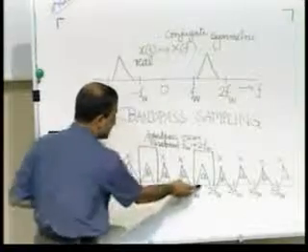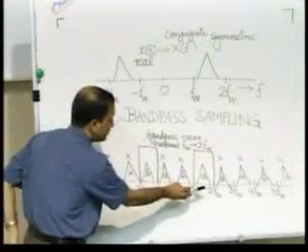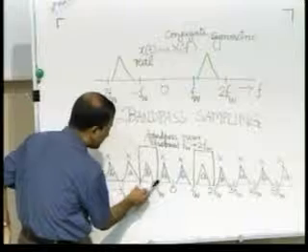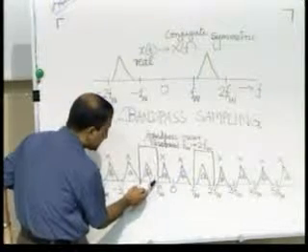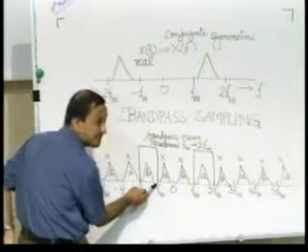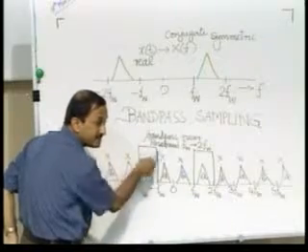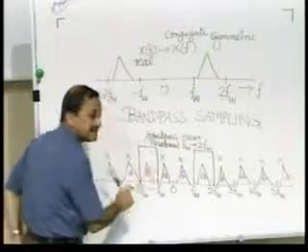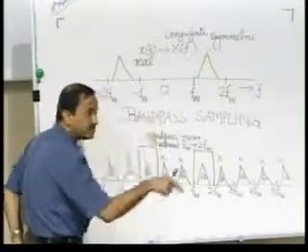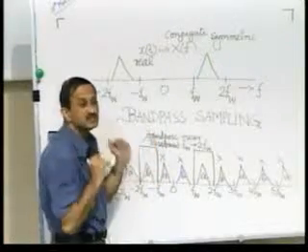You can see here, suppose you sample at more than 2FW, this will come not here but a little bit inside. But if it comes a little bit inside, it's fine because you still have a gap here. So I can make my band pass filter not strictly between minus 2FW and 2FW, but I could bring it a little closer to the spectral ends.